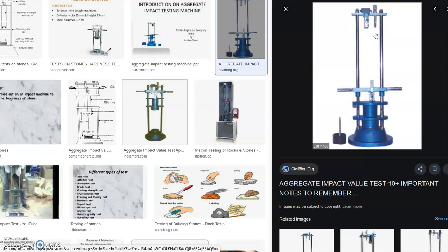So that dropping should be in line with that impact loading. So here you should understand what is meant by impact loading. Impact loading is nothing but sudden loading which happens for a very lesser period, but it happens with a very high intensity. So static loading is there. Static loading in the sense gradual loading over a continuous period of time, slower by slower.